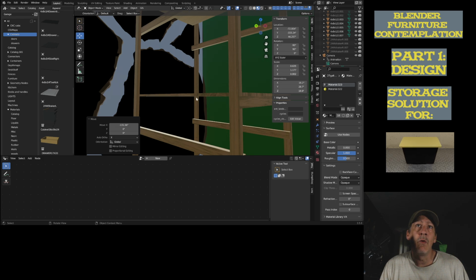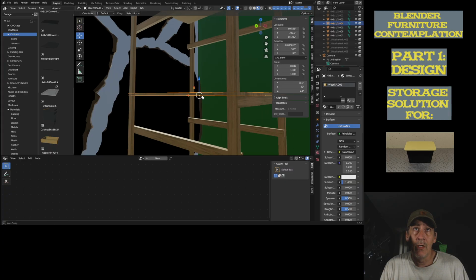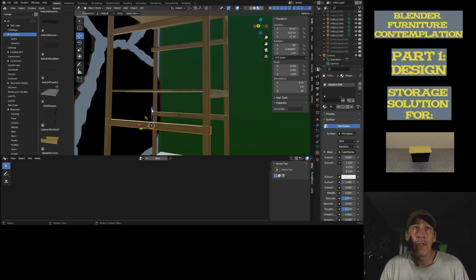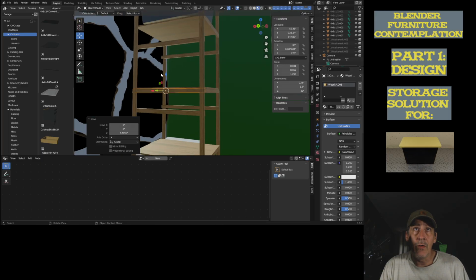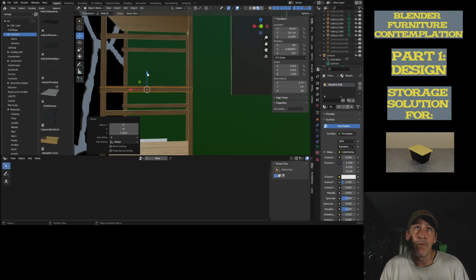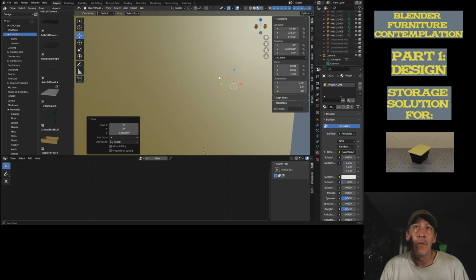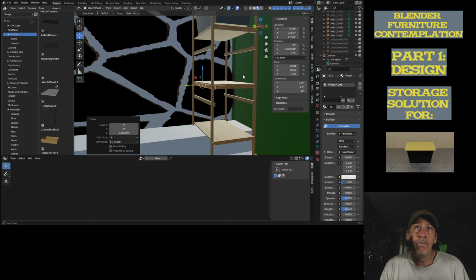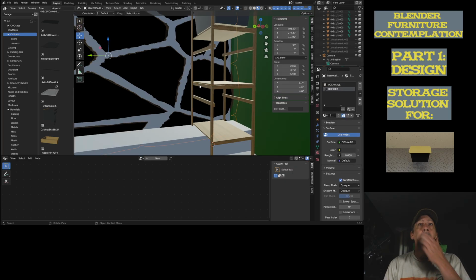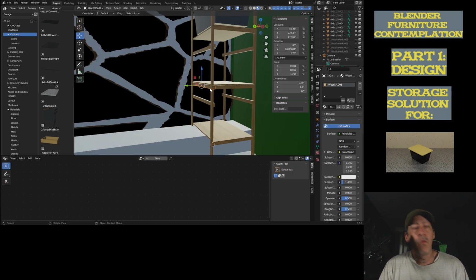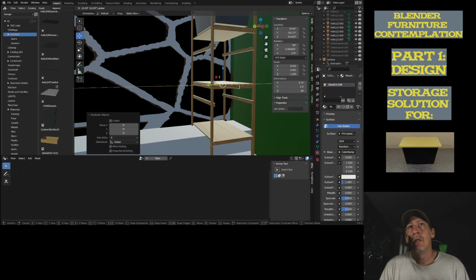I do think angle brackets on these 4 corners would be enough with a 1/2 inch, but we might want to get a rib across there if we do use those for storage. If they are being adapted for shelves, we probably want to have some strength so it's not going to bow in the middle. So what does that do? That gives us